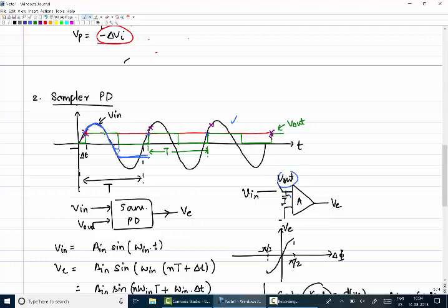So for a given frequency error, you may have some jumps, and then you will have a varying value at the output of the phase error detector, which will represent the frequency error in some range. Okay, it does not say that it is always linearly proportional to the frequency error. It is just proportional to the frequency error. Okay.